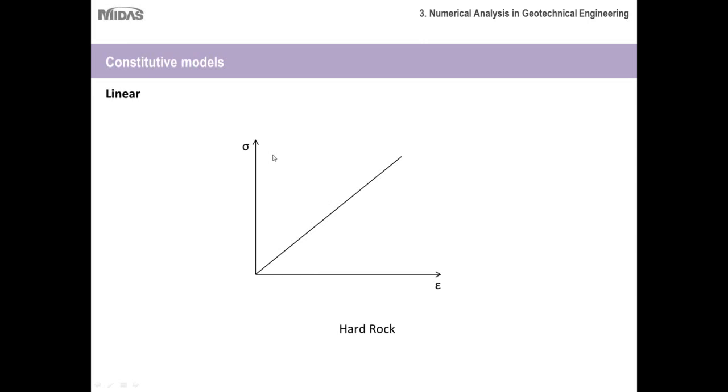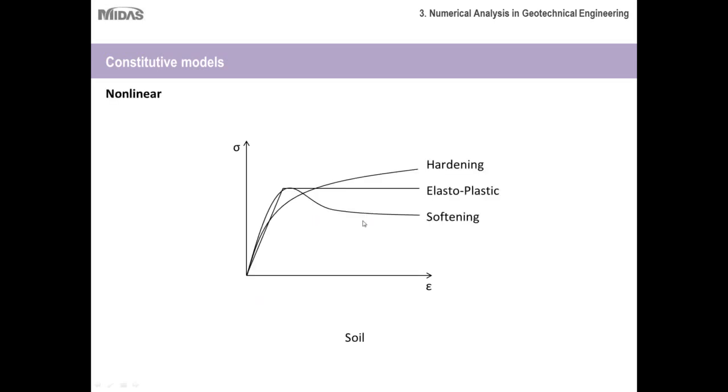Another thing to keep in mind is that hard rock is fairly simple to predict because, as you can see, as the strain increases, the stress increases linearly. So just using this type of relationship, you'd be able to very easily predict the behavior of your hard rock, which makes rock foundations ideal for projects that would benefit from especially simple calculations for stability of the foundation, or stability of the ground foundation.